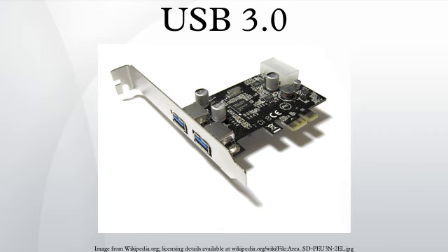Early versions of such boards have a manual switch that can connect the USB 3.0 chip to the processor, which did provide full-speed PCI Express 2.0 connectivity even back then, but this meant using fewer PCI Express 2.0 lanes for the graphics card. However, newer boards used a channel bonding technique that combines two PCI Express 2.5 GT/s lanes into a single PCI Express 5 GT/s lane, thus obtaining the necessary bandwidth from the PCH.